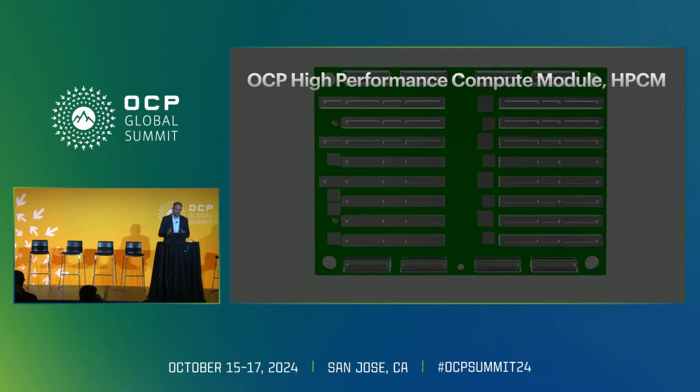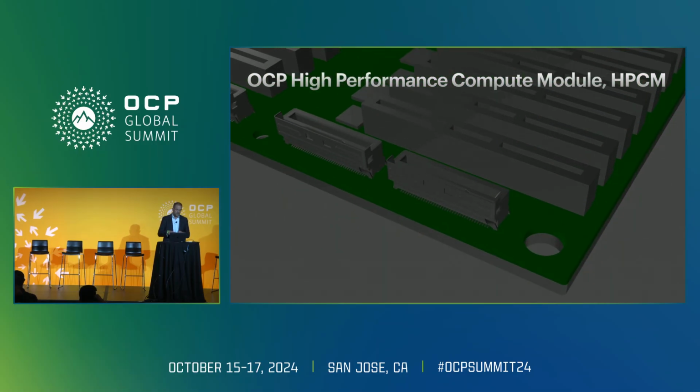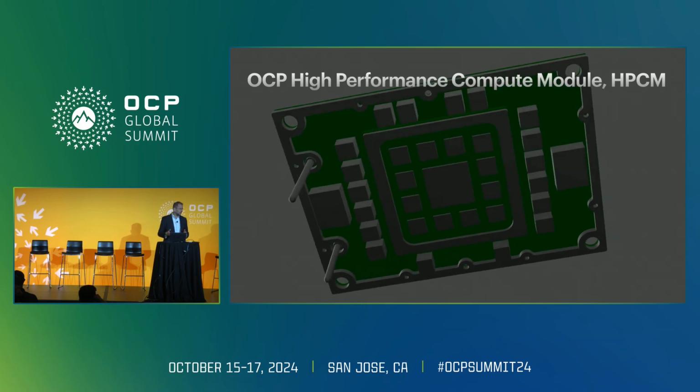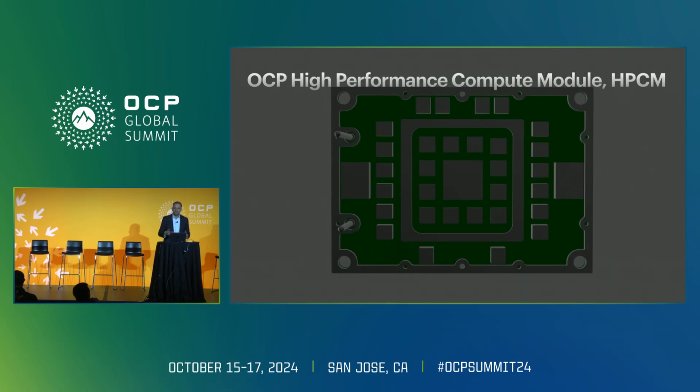The key difference is this doesn't plug into a motherboard. It's got a bunch of backplane connectors for connecting modules together. If you're familiar with servers of today with PCIe Gen 5, you're probably seeing lots and lots more cables in these servers. It's because the PCBs are no good anymore. We need all these bypass cables.